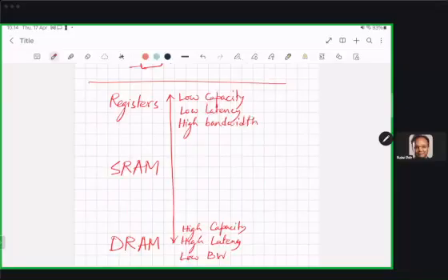basically you see the memory hierarchy which your processors or your computers have. It has the same hierarchy. So the closest thing to CPU is your registers, your general purpose registers, where you want to put all your variables which the CPU can directly access, etc. It has low capacity but very high speed. So if the CPU is working at, let's say, a 2 gigahertz clock, then I can read and write at the same clock from the registers. So high bandwidth also supports that I can read how many registers I want to read. I can read it at that time.